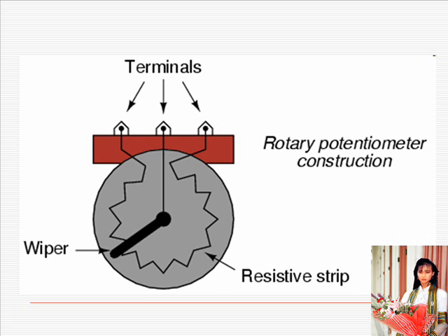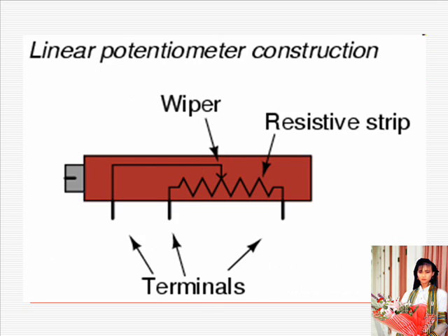Shown here are internal illustrations of two potentiometer types, rotary and linear. Some linear potentiometers are actuated by straight line motion of a lever or slide button. Others, like the one depicted in the previous illustration, are actuated by a turn screw for fine adjustability. The latter units are sometimes referred to as trim pots because they work well for applications requiring a variable resistance to be trimmed to some precise value.